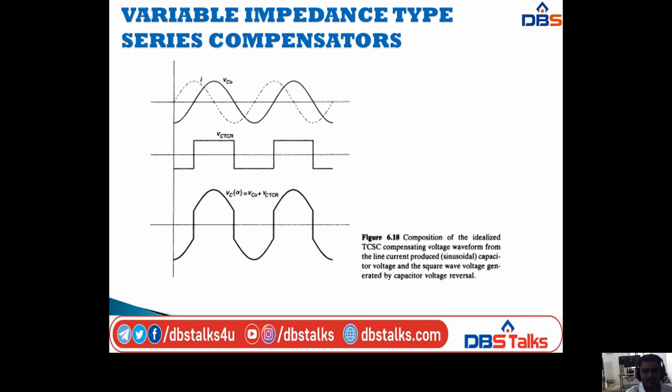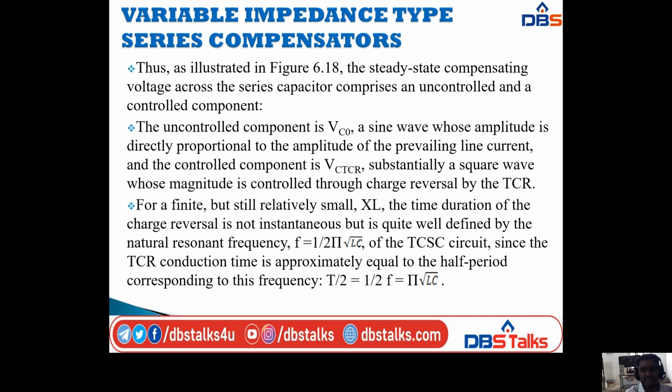For a finite but still relatively small XL, the time duration of the charge reversal is not instantaneous but is quite well defined by the natural resonance frequency, f equal to 1 by 2 pi root LC, of the TCSC circuit. Since the TCR conduction time is approximately equal to the half period corresponding to this frequency, T by 2 equals 1 by 2f, that is equal to pi root LC.